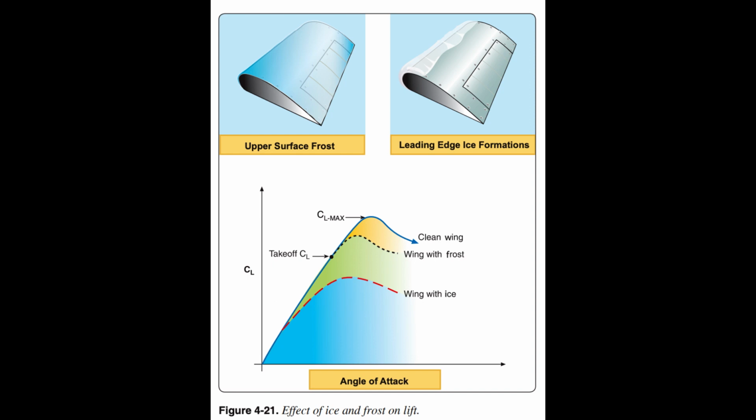Ice on an airfoil can have other effects not depicted in these curves. Even before airfoil stall, there can be changes in the pressure over the airfoil that may affect a control surface at the trailing edge. Furthermore, on takeoff, approach, and landing, the wings of many aircraft are multi-element airfoils with 3 or more elements. Ice may affect the different elements in different ways. Ice may also affect the way in which the airstreams interact over the elements.